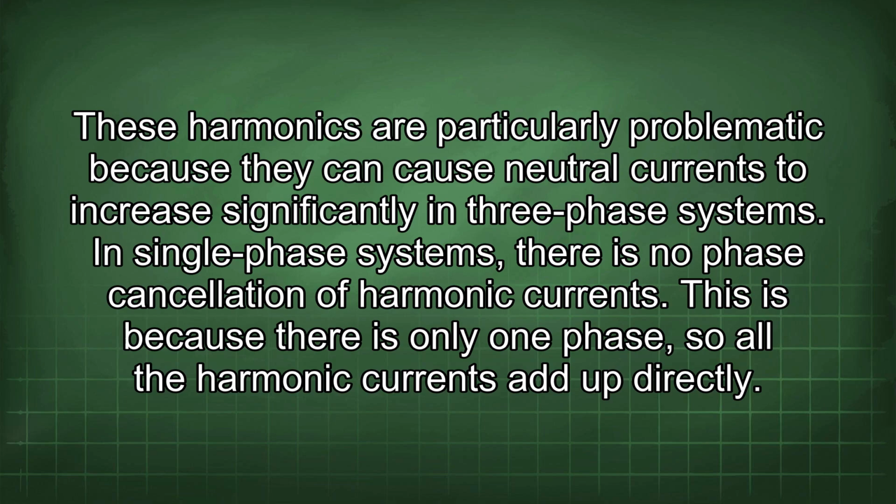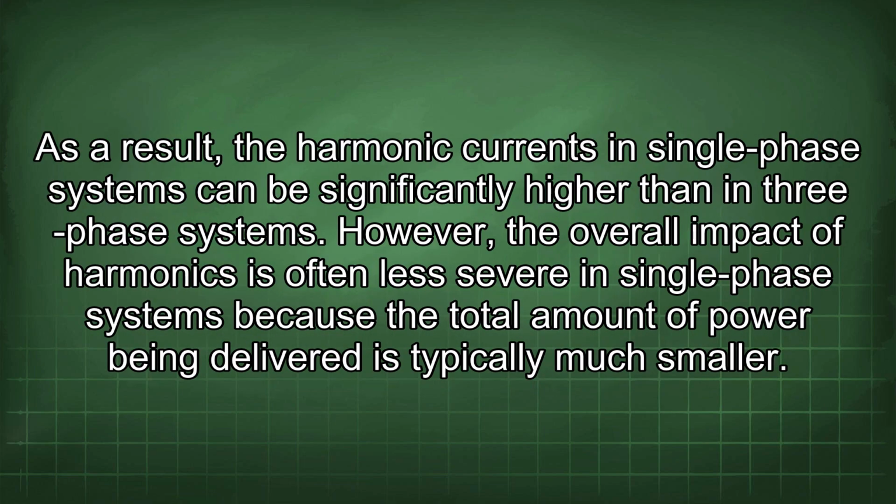In single-phase systems, there is no phase cancellation of harmonic currents. This is because there is only one phase, so all the harmonic currents add up directly. As a result, the harmonic currents in single-phase systems can be significantly higher than in three-phase systems. However, the overall impact of harmonics is often less severe in single-phase systems because the total amount of power being delivered is typically much smaller.